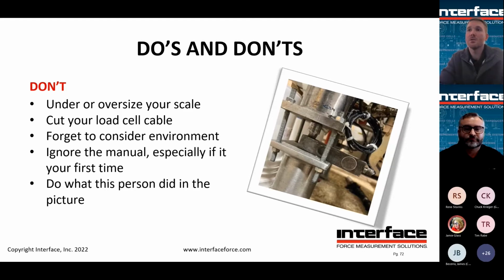Don't ignore the manual. There are a lot of tips and tricks as far as installation, configurations, and how the cells and weigh modules should be oriented. And don't do what this person did in the picture. Look at it closely, but this cell isn't going to give you too much output.